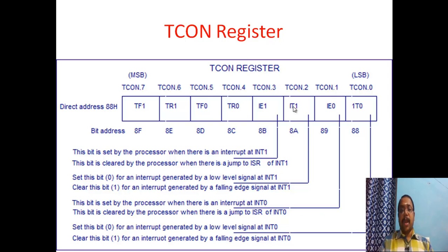See, the timer is also one of the interrupts. So your main program will start the timer work and continue its own work. Once the timer work is completed, the processor will be interrupted. So the timer comes under interrupts, and when you want to use it, you have to enable the interrupt, then only you can use it.